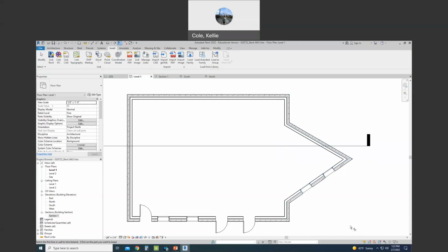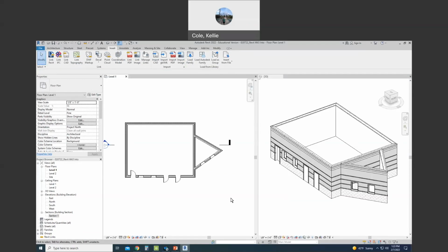Does anyone want me to slice or trim again? Yeah? Okay, let's do it. So I'm going to hit SL for slice, and I get an X-Acto blade type command. Also, I hit escape all the time, and I might not be saying that. I hit escape in between all of my commands. So if you're having trouble getting in a command, hitting escape before you type the command might help.